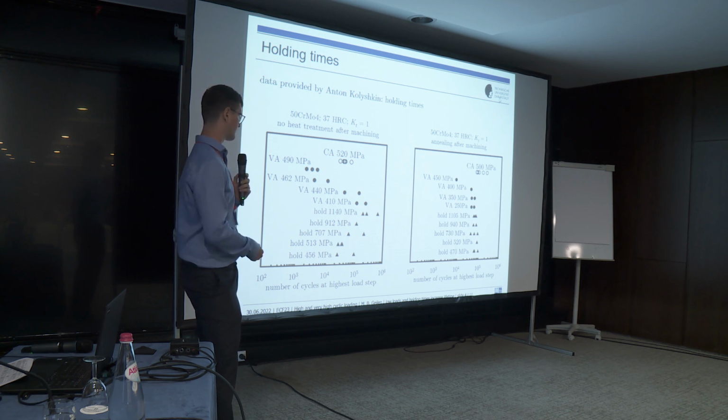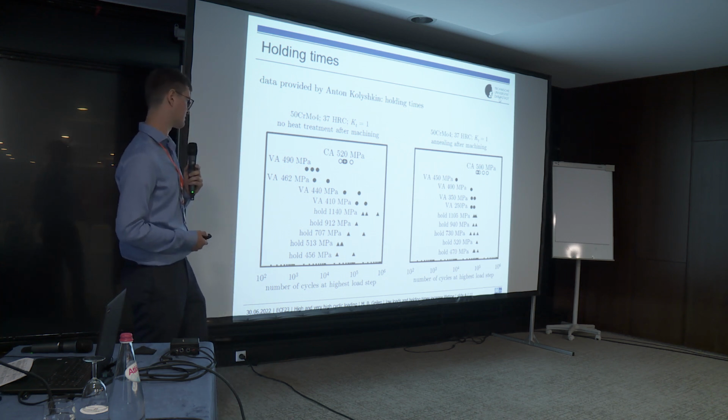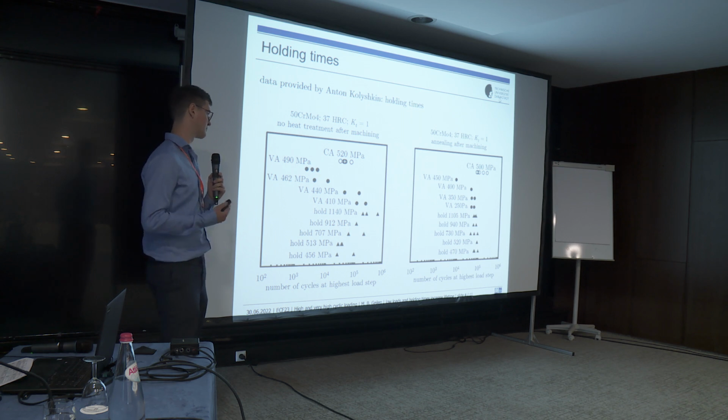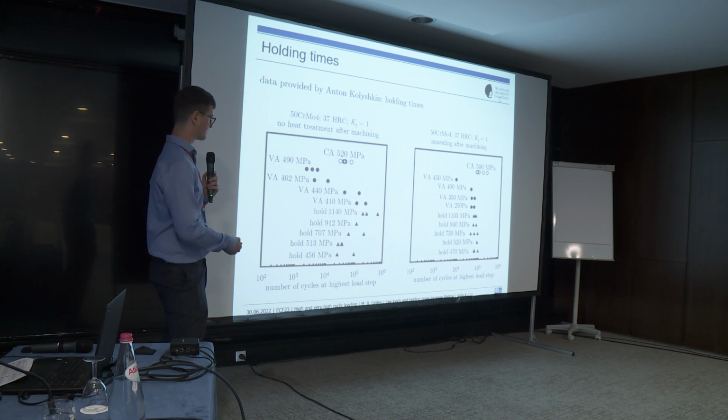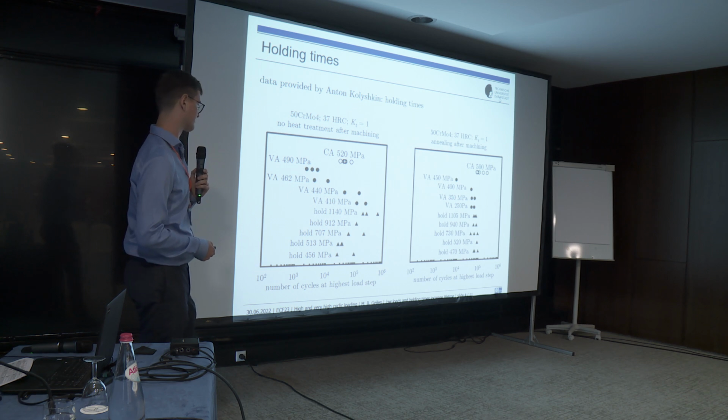The loads were below the higher load of the constant amplitude test, therefore he didn't introduce any further plasticity, and as we're working at room temperature, we really wouldn't expect any influence. However, if the holding stresses were high, we observed a momentous increase in lifetime, which is, of course, the phenomenon that we're talking about today.